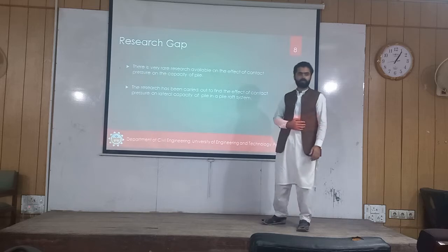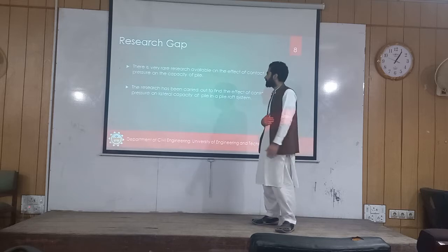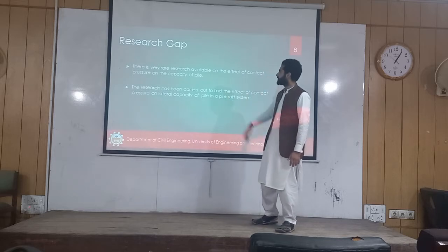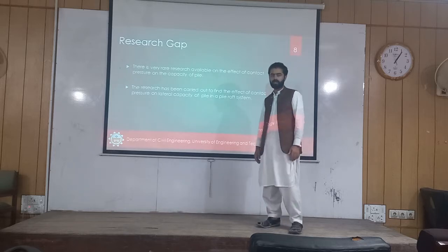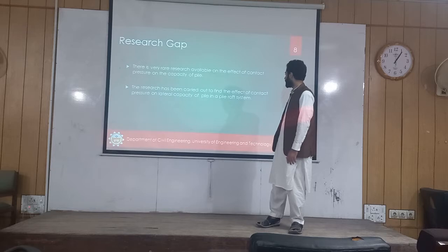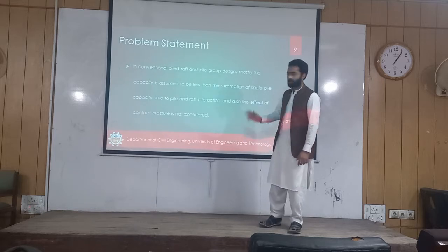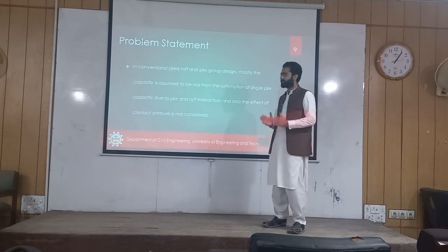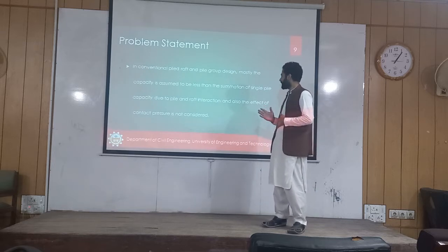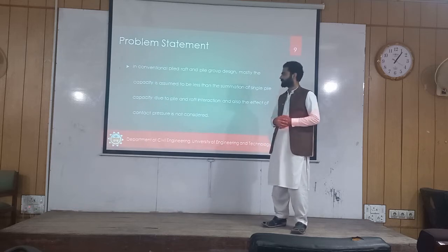Assalamualaikum. My name is Muhammad Zahid, and I will talk about the research. On the topic of our presentation, there is very little research available on the effect of contact pressure on the capacity of piles. The research is being carried out to find the effect of contact pressure on lateral capacity of pile in a pile raft system. Problem statement: in conventional pile raft and pile group design, mostly the capacity is assumed to be less than the summation of single pile capacities due to pile interaction with the raft, and the effect of the contact pressure is not considered.